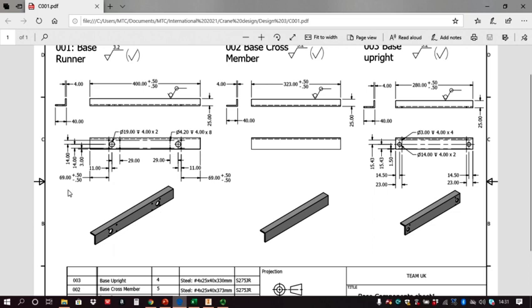Okay, and if we look, you can see there's 69 in from each side, which is 138 off. So if I take 138 off there, it comes down to 260. So it's not quite that simple, because this one is 280 long. But what we could do quite easily, just as I demonstrated on the other one, is move the holes to the position we want after we've shrunken the extrusion.